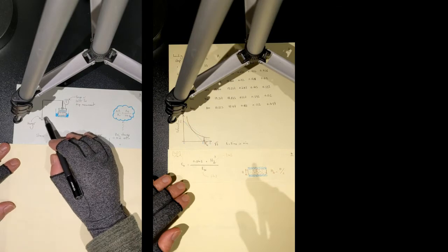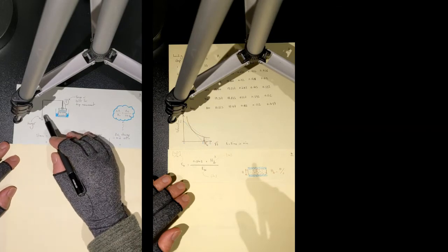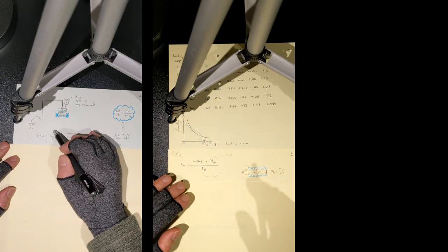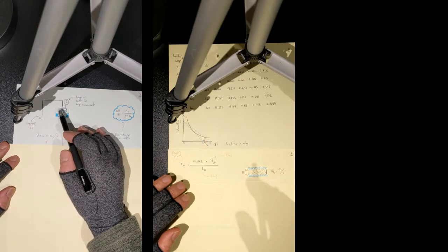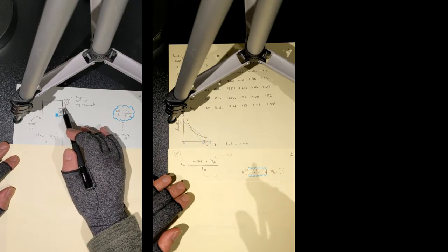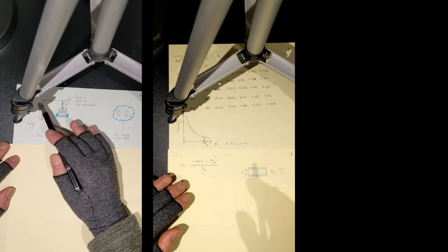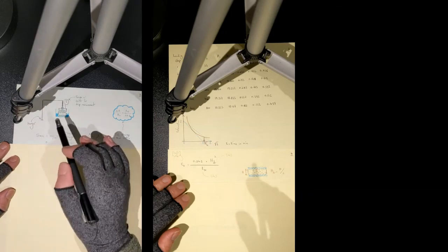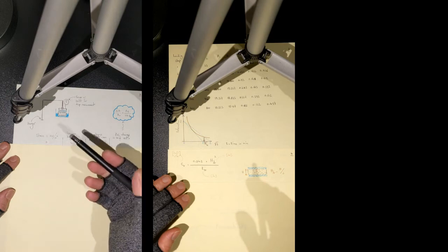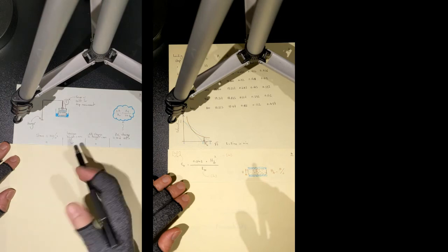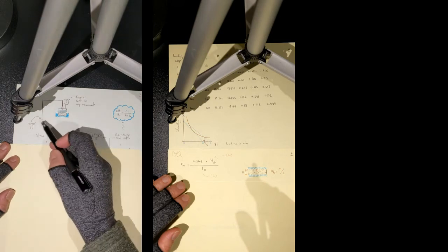It's not really 0 because you have the self-weight of the cap, and normally you put a very small amount of load on the hanger to generate a very, very small stress on the soil sample, just to make sure that all these connections are secure and working. That small pressure, which is something around 2 to 5 kPa, is known as seating pressure. But let's say 0 kPa. It's not really zero practically. I've got to put something here just to make sure that all these connections are working.